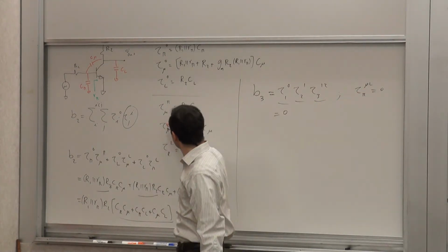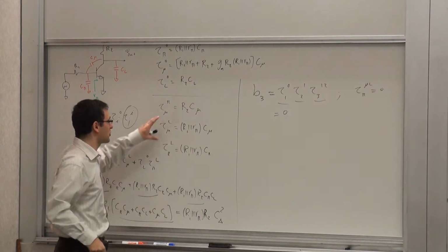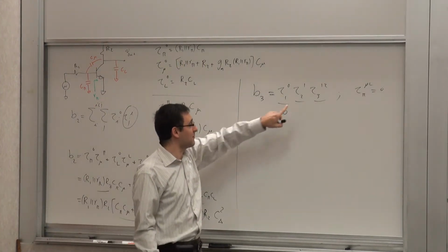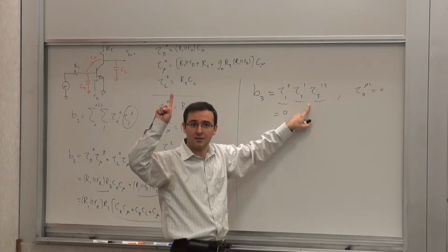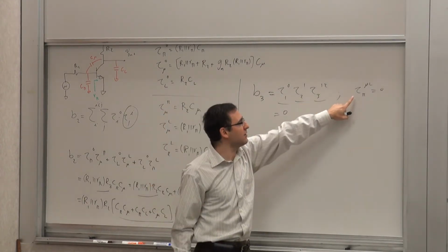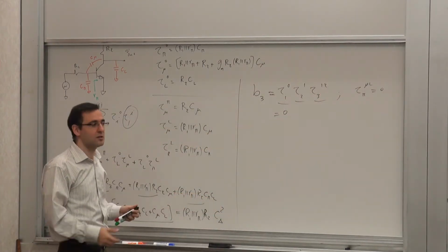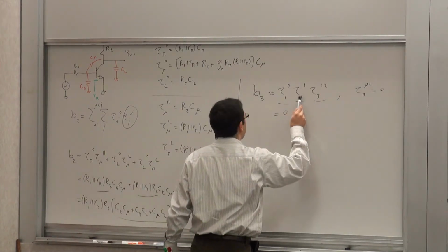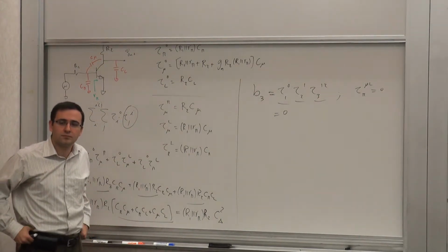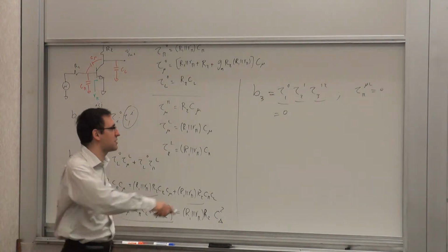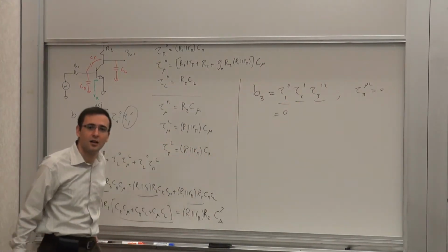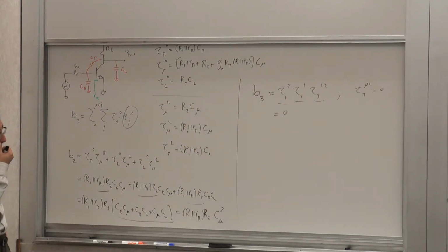You saw that the second order ones were simpler than the first order ones, than the zero value ones. And for B3, the calculation consists of one calculation, because you only need one. Let's say it was non-zero, then you can take any of the two that you've already calculated to calculate that. Because these are the zero value time constants, these are the second order time constants, these are the third order time constants. So it actually becomes simple.